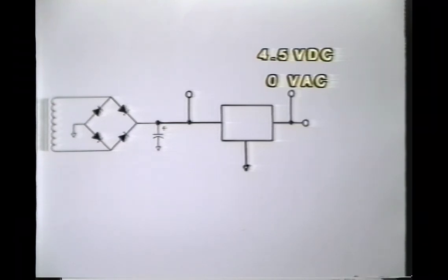switch your meter to read AC volts, remember, check the input voltage first before you change the regulator. Remember, garbage in, garbage out. But if we read a good input, in this case 12 volts DC in to a 5-volt regulator, and a low DC output with no ripple, then the regulator itself has to be the cause of the problem.